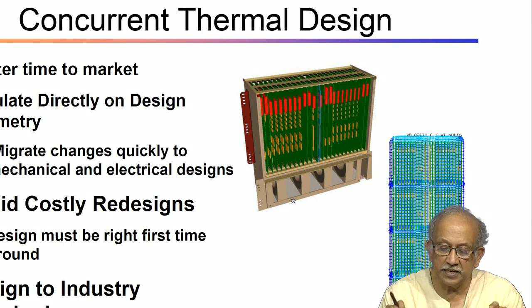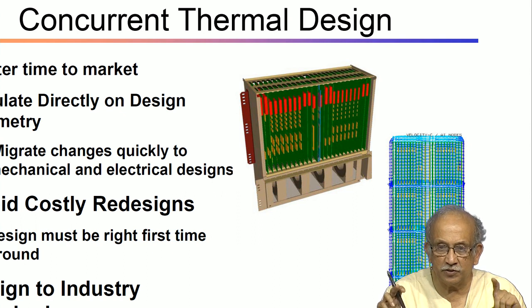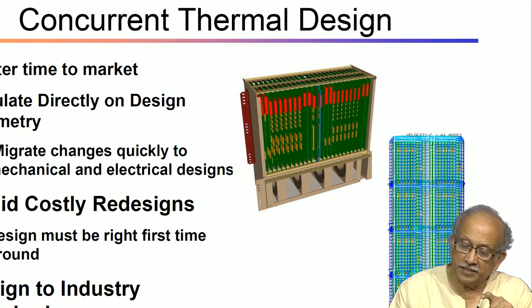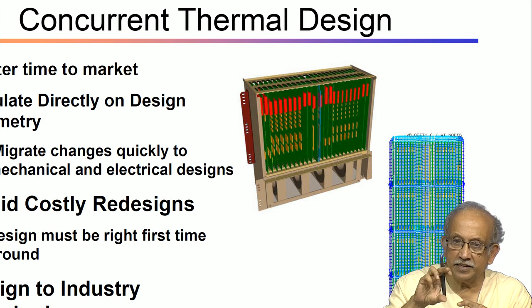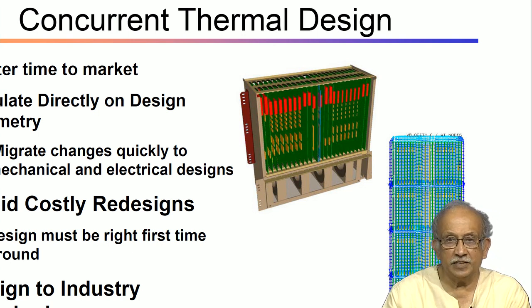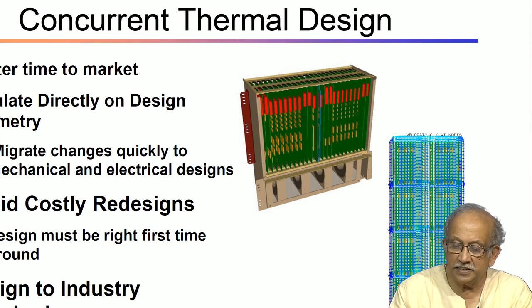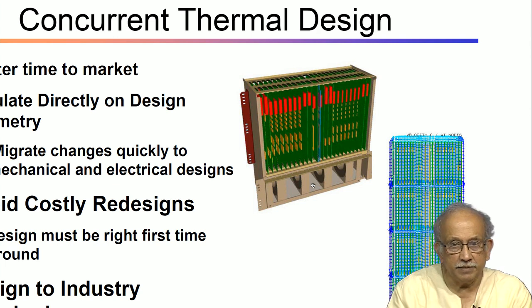This looks like a very odd 4U. Normally we have 3U, and most of the equipment you come across is 1 or 2U. 3U is fairly standard, because the plug-in PCBs have been standardized with a Euro card, which is typically 100 mm high. If you have a 100 mm high by 150, 160 mm depth card, you end up with a 3U. So, usually it is very easy for us to add an inlet from the other side. Same thing in reverse, no?